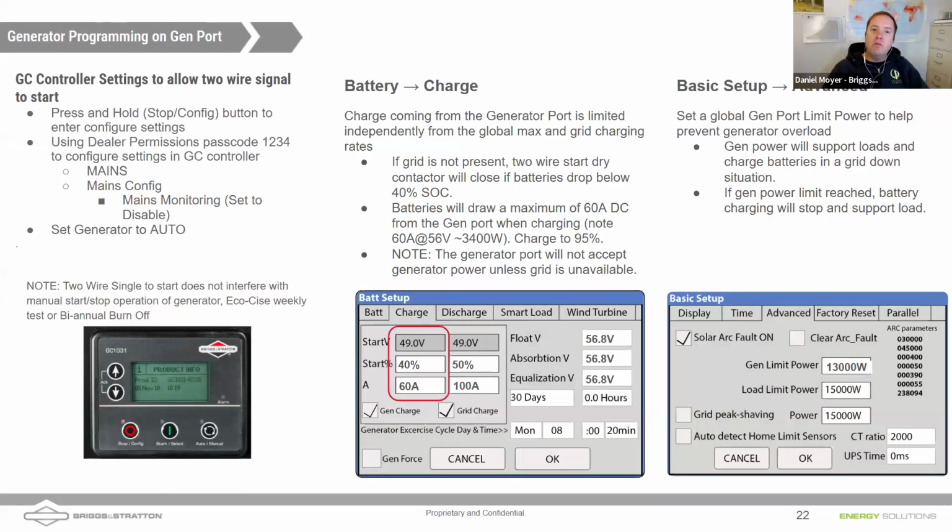Yeah, of course. When a generator-only system is in operation, we've got a generator and a transfer switch. The generator is the device that's looking for the presence of grid sensing. We need to be feeding power to the generator, not only for that grid sensing capability, keep any cold weather kits that are maybe on there, and also keep the starting battery inside the generator charged up, ready to go. If you don't do anything and the generator sees the loss of utility, it's going to start up and then send the signal to transfer and transfer the house.